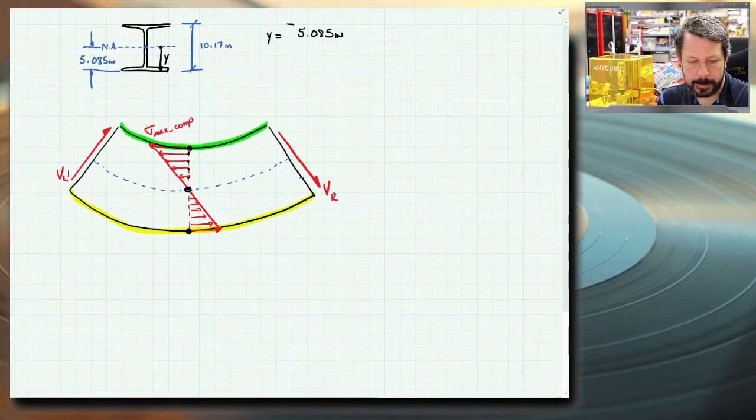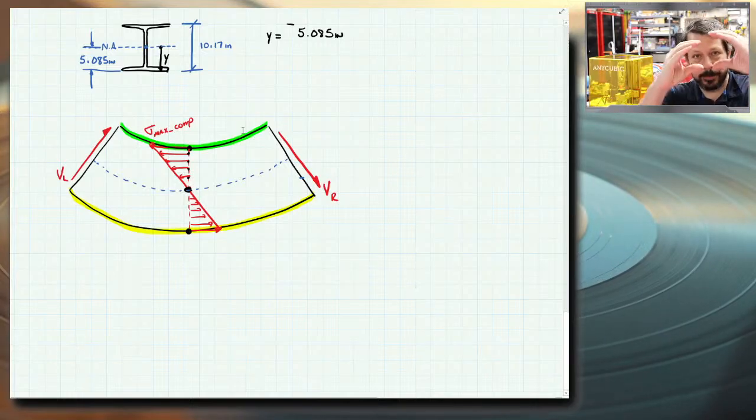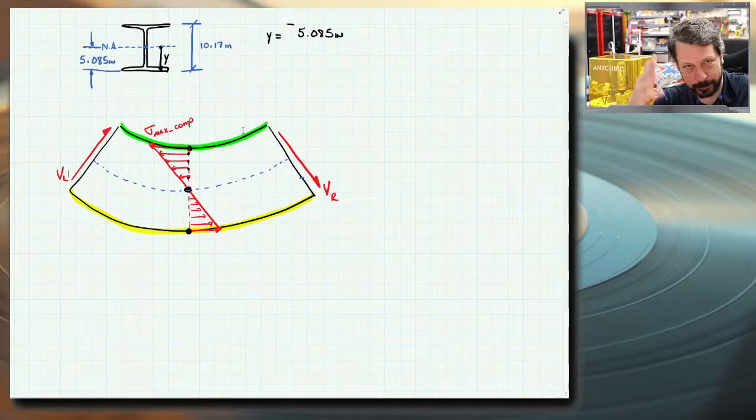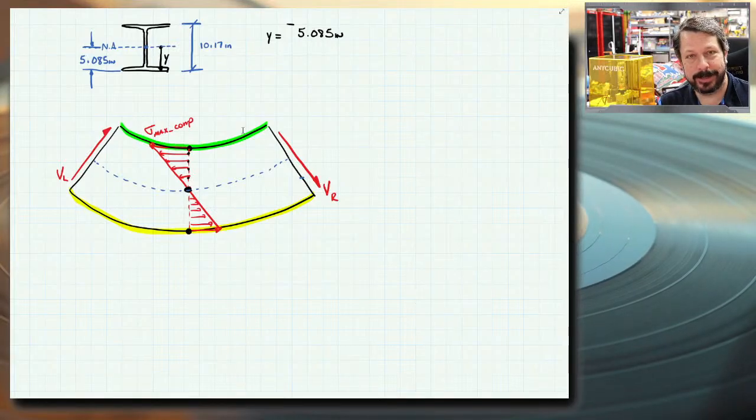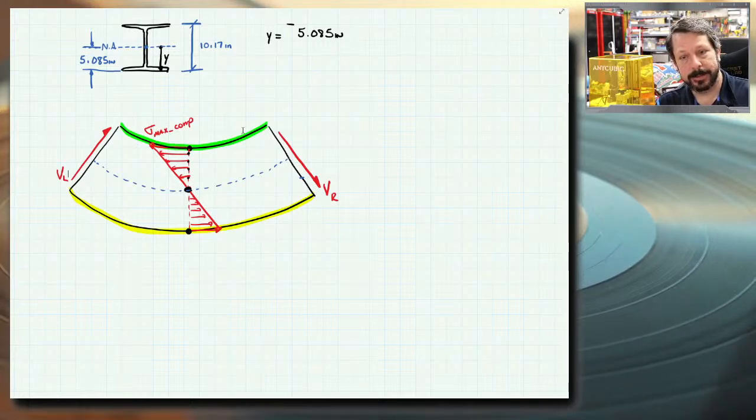But if you think about taking a book, like the phone book, some big, thick book, and it's got a soft cover on it, and you bend the book into a shape like this, in order for the book to bend, all those pages have to slide past one another. And in a beam, they can't do that. They're not individual pages, but they still want to do that. All the different layers still want to do that. And so a shear stress does exist between those layers, like the pages of the book.